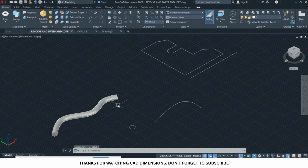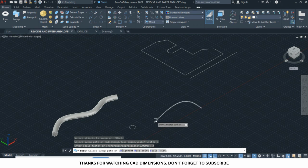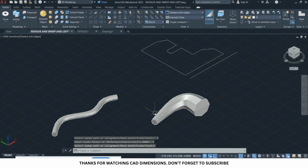So for example, let's go back one step. So I go to the sweep. Okay, I select this, press enter, then I come to scale. For this, let's say I want to enter a scale of 3, and then I press enter, then I select the part. What it basically means is that it started with a scale of 1, but it ended 3 times larger than the first.